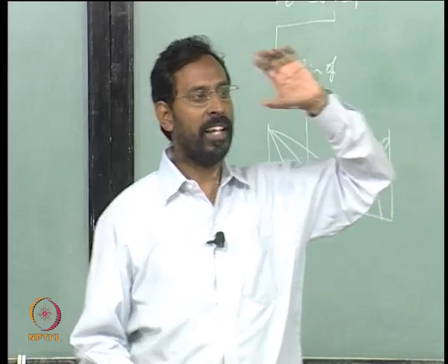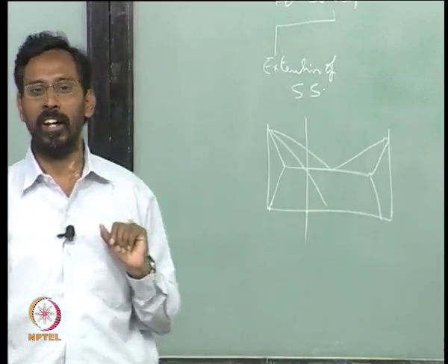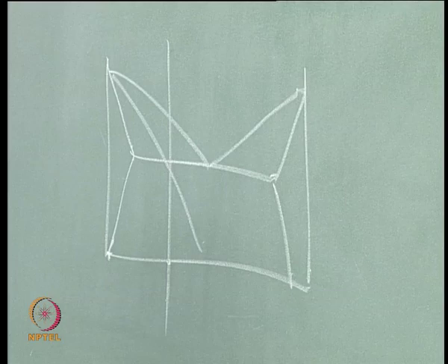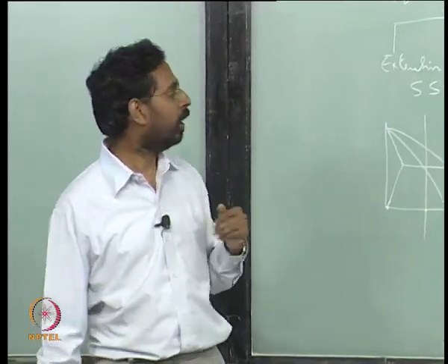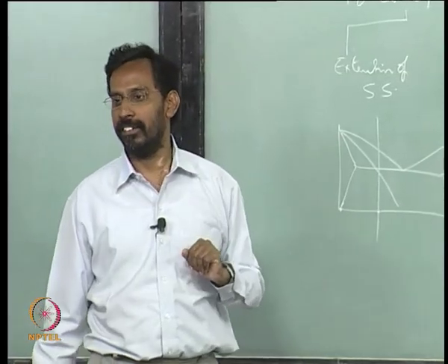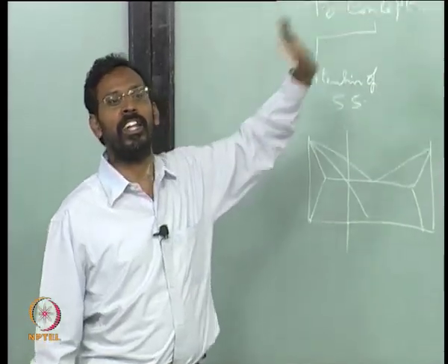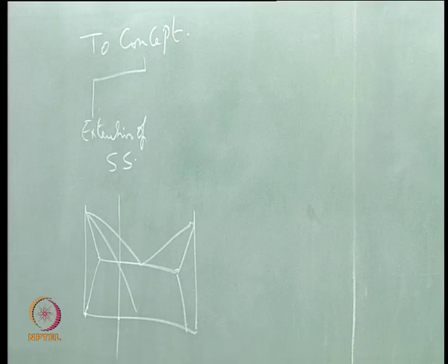So as far as that top portion of the C curve is concerned, we are right, we can say that a faster cooling rate or higher undercooling will give you fine grain sizes, but that has nothing to do with the T naught concept. It is just higher undercooling leading to a higher nucleation rate, and as a result finer grain size.